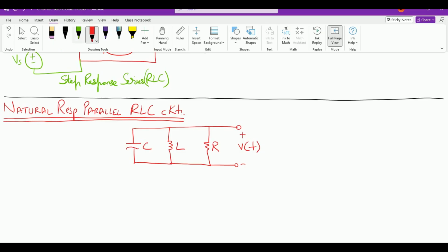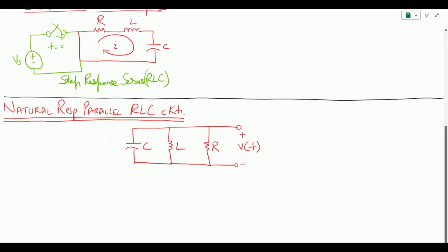Keeping in mind that for these elements, since there is no voltage source, what is going to be the energy available on these storage elements, which are the capacitor and the inductor? The initial voltage appearing on the capacitor will be V0, and the initial current flowing through the inductor will be I0. This appeared because the source was abruptly removed from this configuration. And now we want to figure out the equations for the unknown voltage when the storage elements are about to